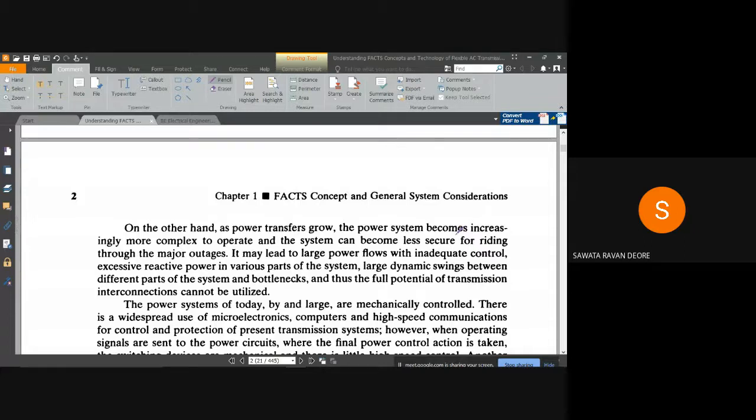That is what we call a bottleneck, means the network is there and one particular line is acting like a bottleneck. Its power handling capacity is such that under different generation scheduling cases, in those load flow circumstances, that line is getting overloaded and we can't operate it. So obviously we need to plan or develop another parallel transmission line along with it, or modify the parameters of other lines or that line itself such that the bottleneck can be removed.